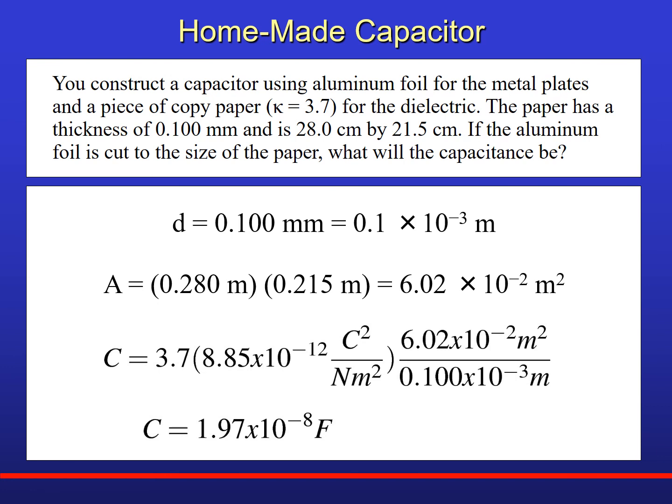Now, if you ever go into the lab, go into the electronic shop, pick up a capacitor, I've never seen one that had scientific notation listing. They will use units like microfarad, nanofarad, picofarad. You won't see scientific notation. So the closest one to convert this would be nanofarad, which would be 10 to the minus 9. How would I get 10 to the minus 9?